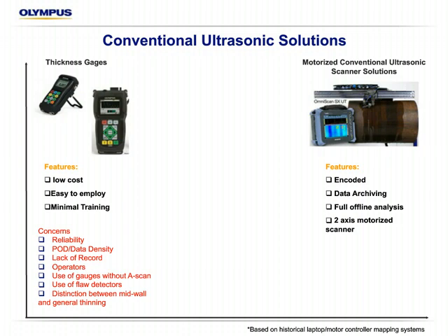As for the operator level, most of these people are on the baseline of doing thickness gauge surveys. They might only be qualified level 1 UT thickness gauge versus being a level 1, level 2 shear wave with more experience doing other types of ultrasonic tests. A real big concern in the industry is the use of a gauge without an A-scan.